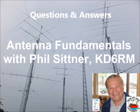Sometimes you run out of markers. Oh, okay. So right now, my antenna, I moved its resonant point to 7.5 megahertz. That's right here, which is position number 6. Position number 6, you see how close that is? The dead center. Up here it's too long, down here it's too short. So it's right on that line. And at this point on the line, it's exactly 50 ohms. So this antenna is 50 ohms, it's not too long, it's not too short, at 7.5 megahertz.